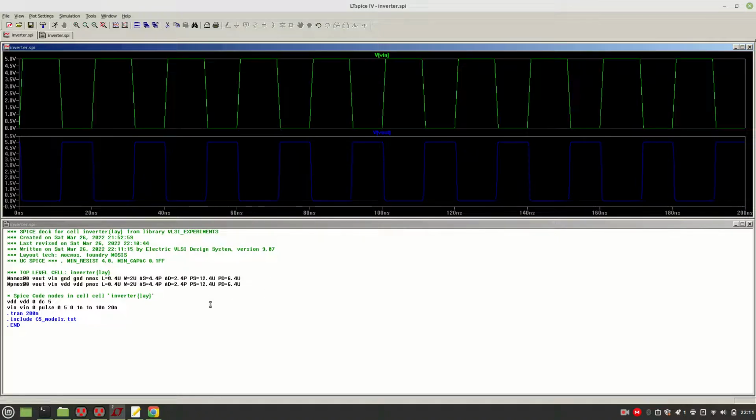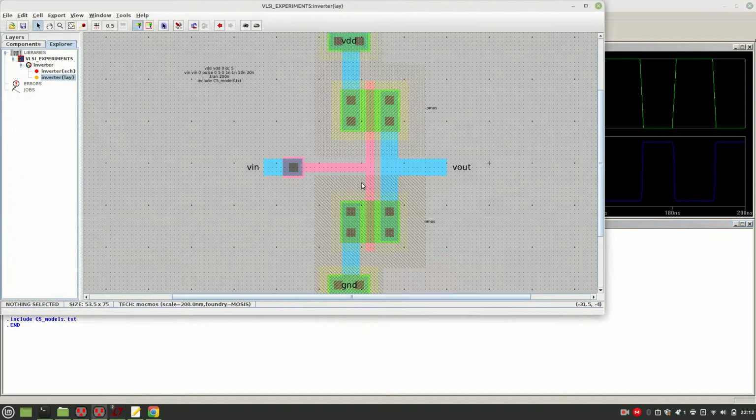So this is for W N is equal to W P. So okay, so here W N is equal to W P. But if you change this, the capacitance may change, the parasitic capacitance may change. So better change in this schematic, like in this layout we need to change, like make this as a 10, 20 like that.